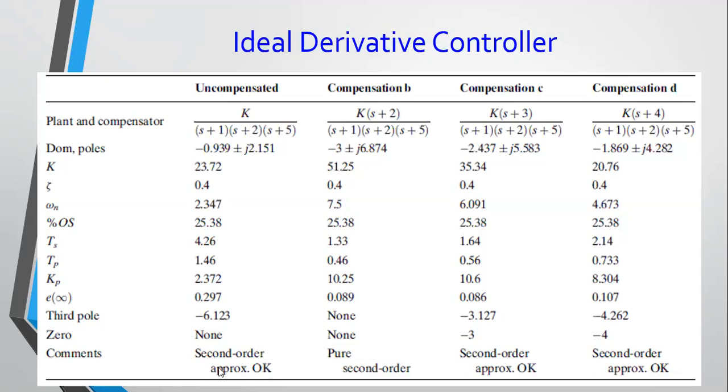Okay. Now, a small comment here: you can of course calculate the Kp, your static error constant. You can see clearly your Kp is also increasing, even if you're not tackling your steady state error, because here we're dealing with transient. As part of introducing the zeros at different points, your Kp is increasing, and subsequently your steady state error is reducing. But that's not to say it would always reduce.